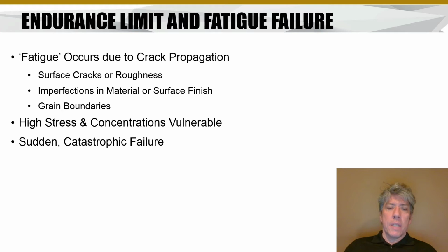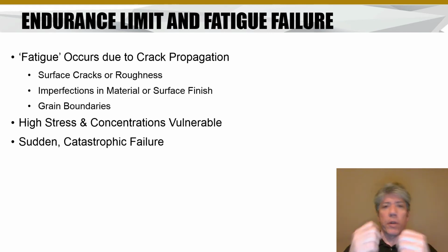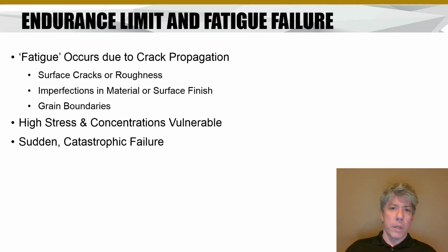Alright, so basically fatigue occurs due to crack propagation. Now they used to think that it was crystallization of the metal because of the way that the failures looked. You'd have a shaft or something broke apart, you could look at the ends and it looked like there were crystals forming or something. So it's called crystallization, but that wasn't really what was going on. The metal was not crystallizing. Well, what happened instead is there's very small, minute cracks, and those cracks propagate, and fatigue is the name we give that, really. The cracks can occur from many different sources.